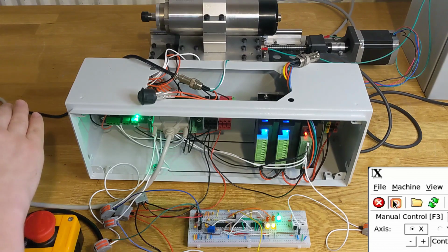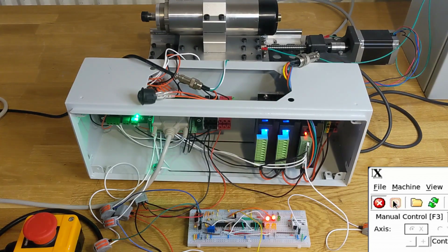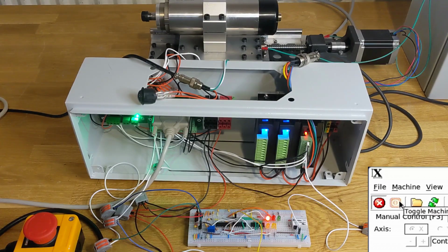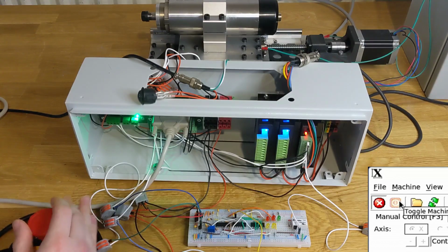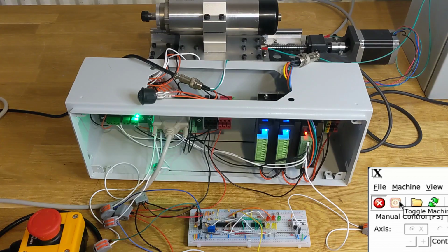Now let's check the e-stop. Yep, nice. The e-stop LED illuminates and the state matches in the UI. Because of how we've configured our machine in LinuxCNC, the enable signal goes to false and the charge pump stops. So there's no lockup state on the safety module. Resetting the e-stop therefore doesn't start the machine up again. It just puts us back into a state where we can start up the machine.